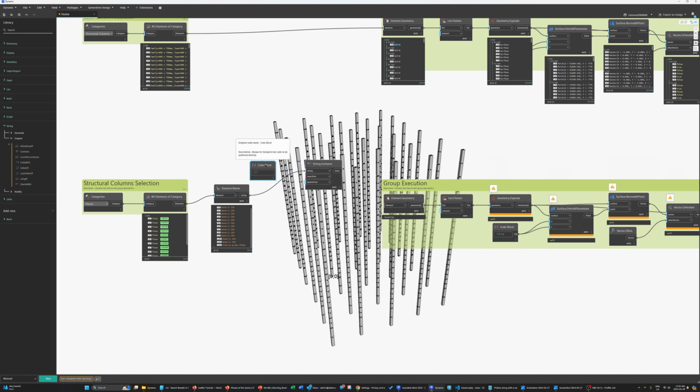I'm going to just put in quotation marks, slab. You can ignore the case, by default it is on, but I'm just going to set this to true. I want to ignore the case, I want to be able to search lowercase. You never know within a project. Actually, slab is not the correct one. I want to look for grade. And I'm just going to put this as an example, with a capital G. So obviously, if I go like this, it should provide me with all false except one true.